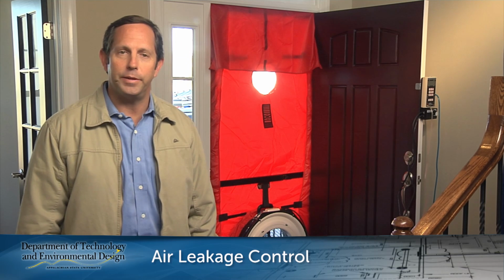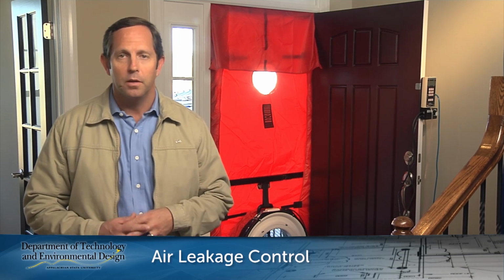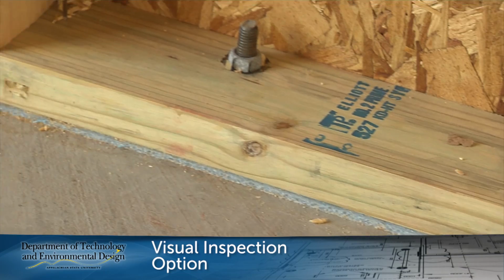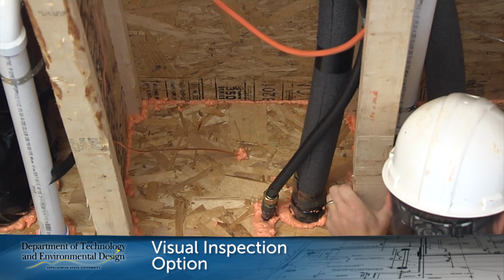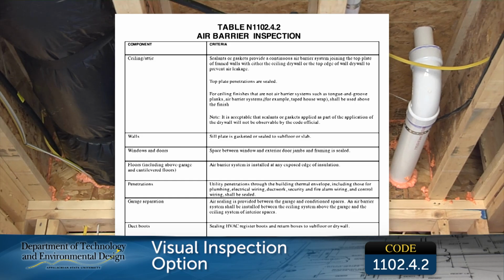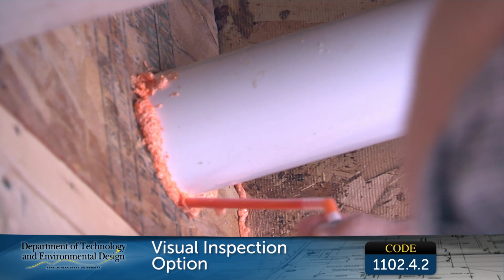One of the last things to be checked is the building's air tightness, which is required to be demonstrated. This can be done 2 ways. First, by visual inspection during the building process. The building must comply with the insulation enclosure and air sealing provisions we talked about earlier, as well as address the applicable items from Table 1102.4.2. The air barrier inspection list then must be certified by the builder, permit holder, or registered design professional.